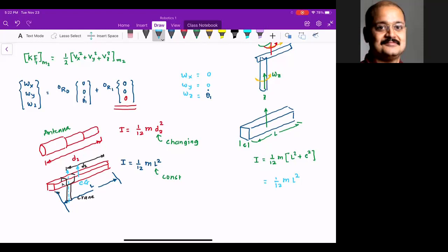So if crane is extended, at the CG of the crane, the mass moment of inertia is the same. But when you look at the total kinetic energy, or total momentum, the moment of inertia at the rotation joint is more because it's mass multiplied by the radius of gyration square. And you know which term will take care of that? Translational velocity will take care of that.